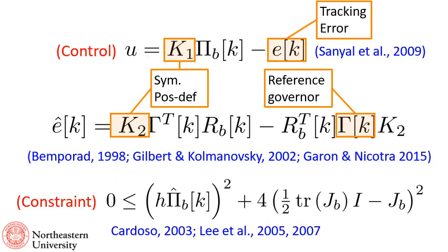The issue of constraint satisfaction in nonlinear systems, including affine and non-affine control systems, and its separation from the issue of closed-loop system design have been addressed very extensively in nonlinear control theory. Almost all of these works do so by including a filter, which is an auxiliary nonlinear device that operates between the reference command and the input to the closed-loop system. A similar approach is adopted here.